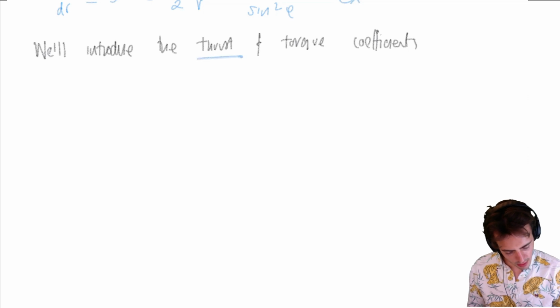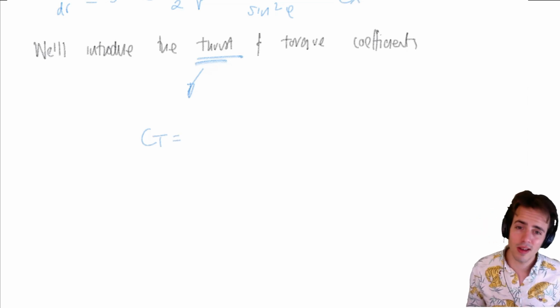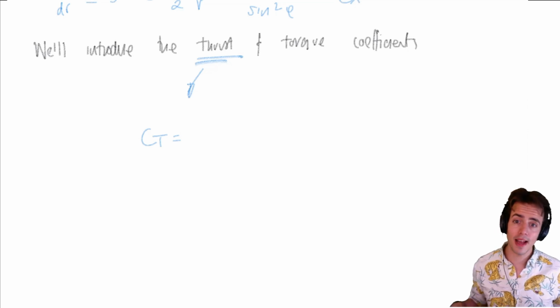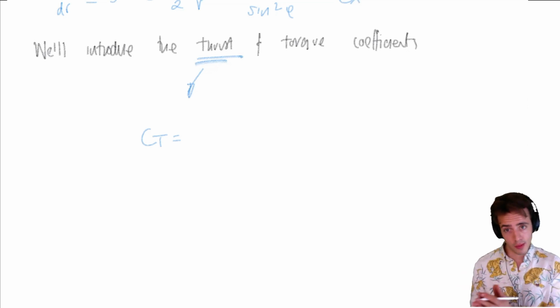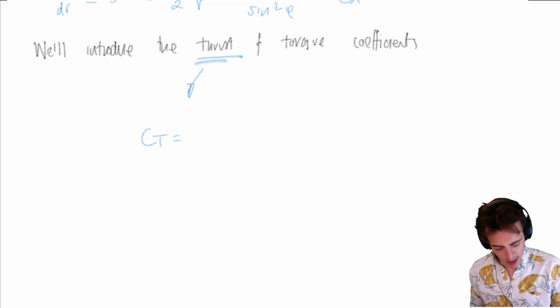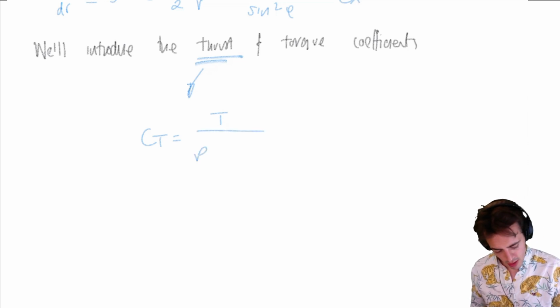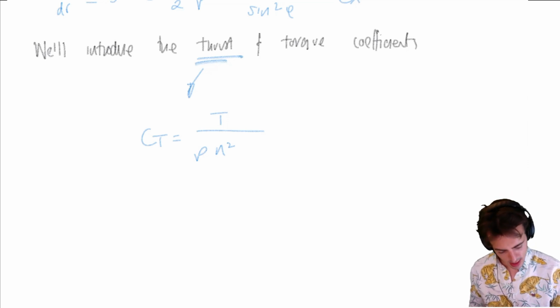So thrust coefficient, CT. Now this is where the nomenclature for propellers is such that someone chose to use a divisor that made sense at the time, but is discordant with some of fixed wing aerodynamics now. So we say that it's equal to the thrust divided by rho n squared, so that's revolutions per second squared, and then diameter to the 4.